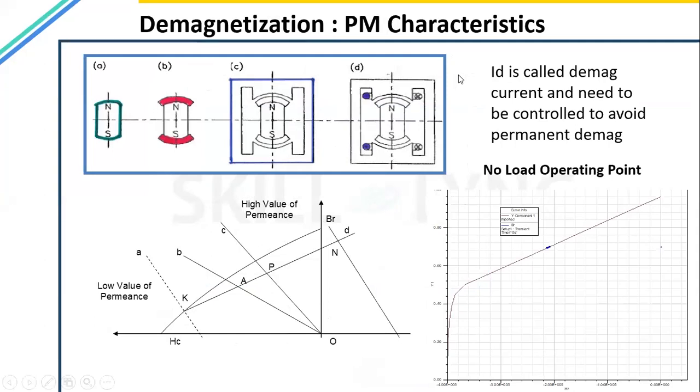The other thing is the demagnetization of the machine. When we use permanent magnets, you can see here a simple topology where the permanent magnet is being used differently. This outer frame is a high permeable steel, and then there are some coils here where we also create some field due to the current, which demagnetizes this magnet.